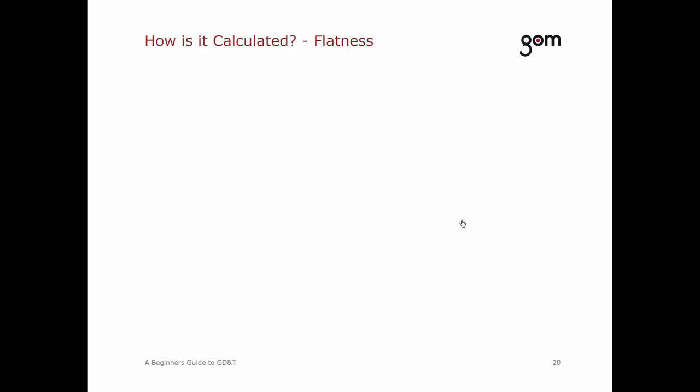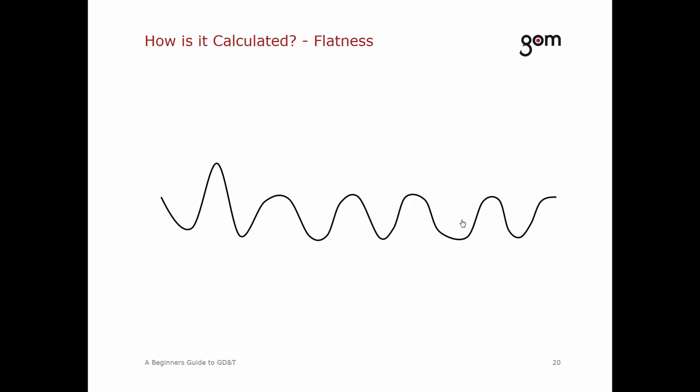So how is it actually calculated? Well, here you see the exaggerated form of the plane, represented by the captured and selected measuring points. Now the software uses a Chebyshev best fit algorithm to compute the center of those points. The Chebyshev best fit computes the resulting fitting element in such a way that the maximum distance is the smallest.